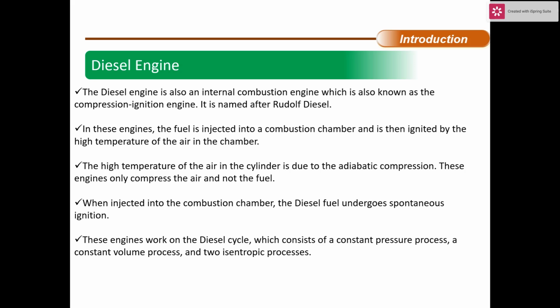In this engine, the fuel is injected into the combustion chamber and is then ignited by the high temperature of the air in the chamber. The high temperature of the air in the cylinder is due to adiabatic compression. These engines only compress the air and not the fuel. When injected into the combustion chamber, the diesel fuel undergoes spontaneous ignition. This engine works on the diesel cycle, which consists of a constant pressure process, a constant volume process, and isentropic processes.